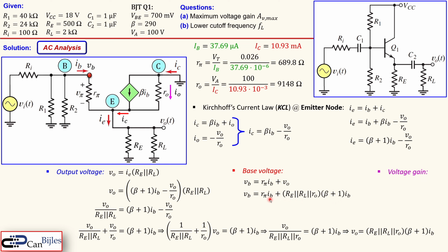Alright, now the voltage gain we can write down in a more convenient way because we need to go all the way from the input VI to the output, and we can do it in 2 parts. We can say VO over VI is VB over VI, so going from here to this node, and then from that node to that node. That's shown here, so VB over VI, that's the first part. And then from that node to the output, which is this part. So I have already this, because that's just this one divided by that. We only need to do the VB over VI.